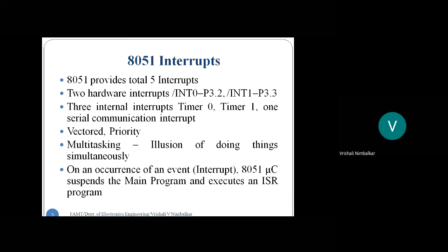In the 8086 microprocessor, students, do you all remember vectored interrupts and non-vectored interrupts? In the 8086, there was one non-maskable interrupt, NMI, and one maskable interrupt, INTR. These were the 2 hardware interrupts, and the remaining were 256 software interrupts.